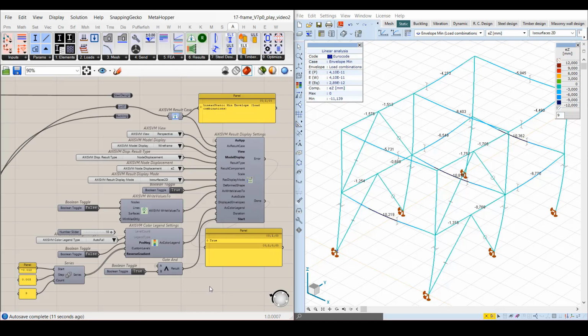There is still one input parameter to be mentioned, the duration, which is practically a delay in seconds. This means that the done output of this component is changed to true with the given delay after the display settings have been applied. Thus, the user may keep the results on the screen, for example, between two finite element analyses.